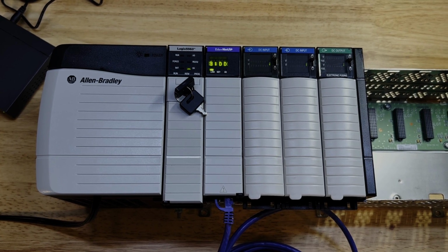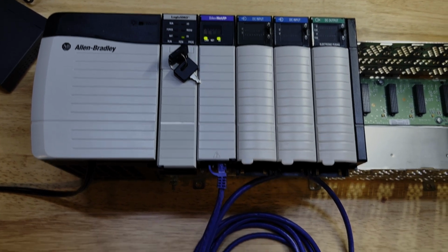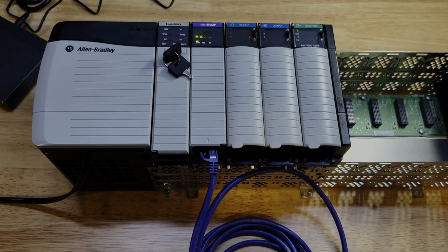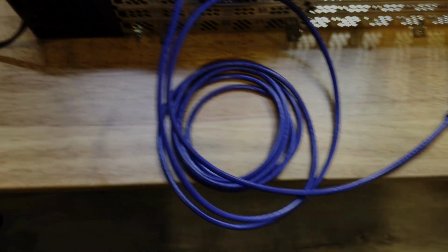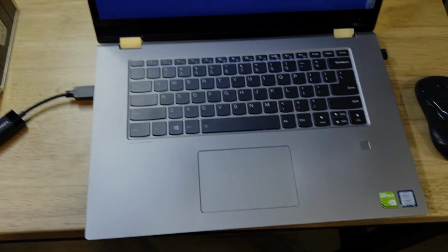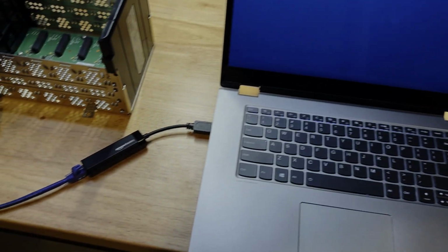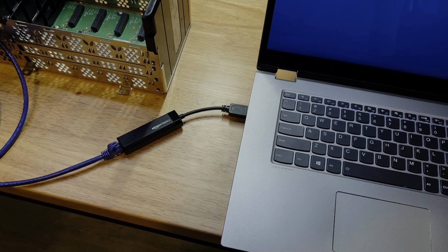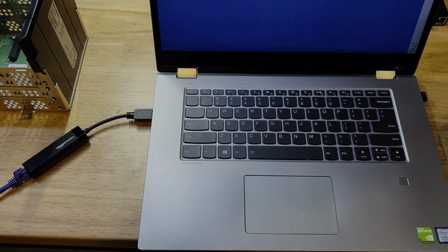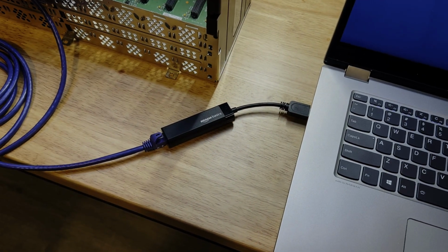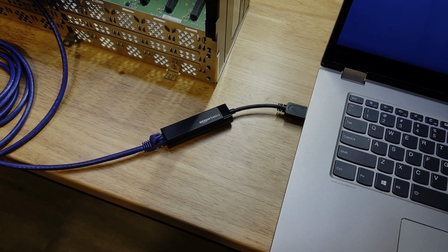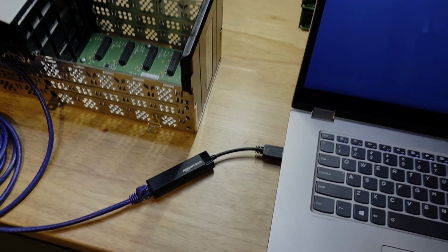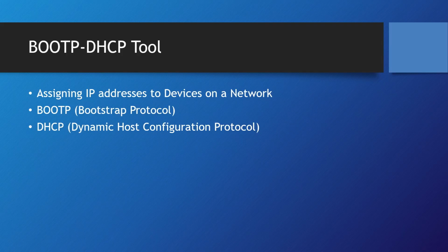As you can see, this is connected with a standard Ethernet cable from the PLC network module over to my laptop or engineering workstation. My laptop does not have a built-in Ethernet module, so I'm using this simple USB network module I received from Amazon. Note that it's typical with any modern network module that they will auto-negotiate to a crossover scenario when directly plugged in to a device. Now that we're physically connected to the PLC, we can logically connect through the software.